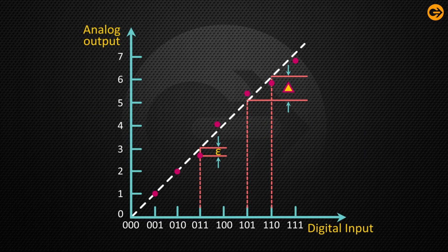The figure here states the output voltage of 3-bit unipolar DAC. Here, the horizontal axis states the input bit combinations with fixed interval separations in order of numerical significance, and vertical axis represents the analog output. The output voltage for each input is indicated by a dot. Since the DAC is not ideal, hence the dots do not follow a straight line.